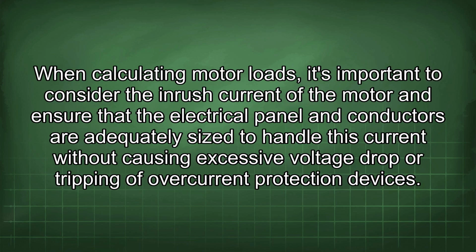When calculating motor loads, it's important to consider the inrush current of the motor and ensure that the electrical panel and conductors are adequately sized to handle this current without causing excessive voltage drop or tripping of overcurrent protection devices.